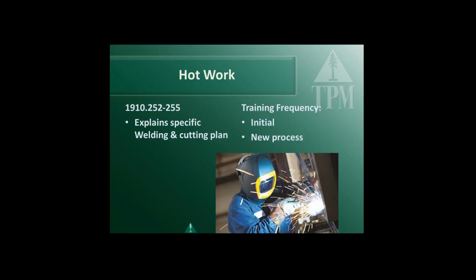Because if you're welding stainless steel, you release chrome into the atmosphere and you're breathing that in. So then you get into respiratory protection and all that kind of stuff. There's engineering fixes where you can use filtration, air systems. There's portable ones that can control that atmosphere. So hot work is one area that needs training on initial and then new process.